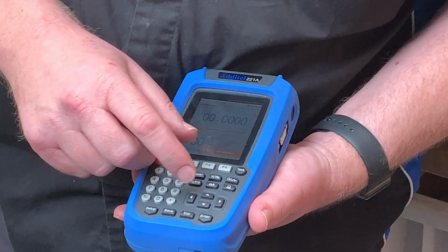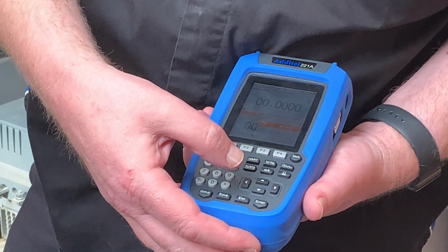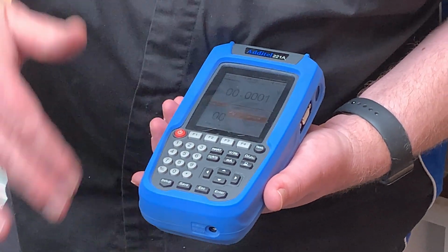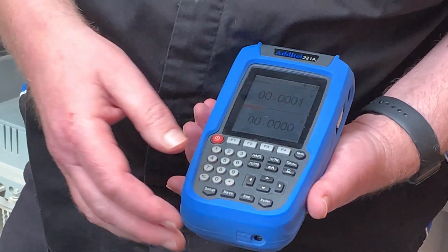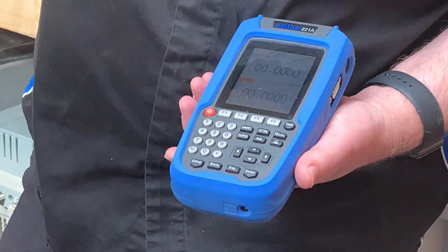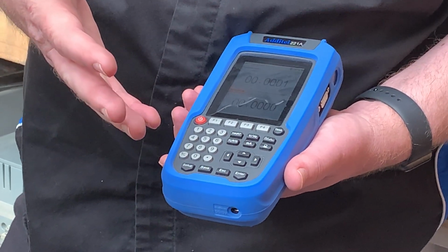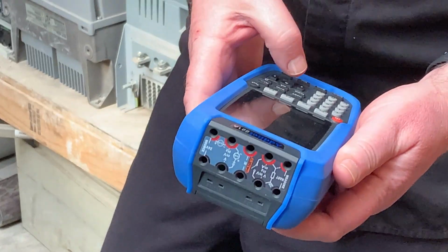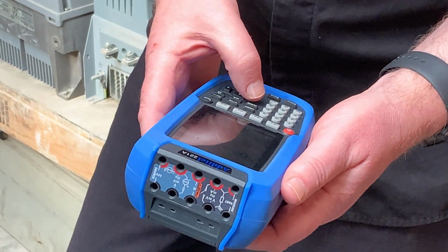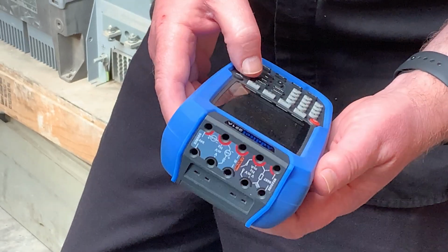So if you've got an RTD, you might look up a table. We might just go to volts. And if you happen to know that a PT100 is 100 ohms at 20 degrees C, which it is, you could then put in 100 ohms and see what it does at 20 degrees C. And again, make it ramp, make it do things as well. So we could go, sorry, I'm saying volts, not ohms. Duh, wake up, Greg. So we're going to ohms for a PT100, 0 to 400 ohms.